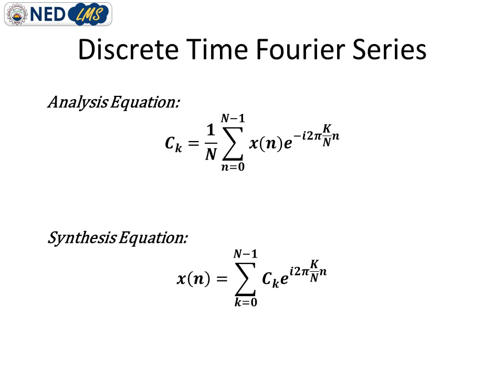Another technique is the discrete time Fourier series. In the analysis equation we use the summation sign, which represents the discrete function, and as we are dealing with a series, which means a periodic function, we represent the limit as n equal to 0 to N minus 1, not the infinite limit, because we have a specific time period. And in the frequency domain representation, given by the synthesis equation, we also get a discrete plot and a periodic representation, represented by summation as well as the finite limit.